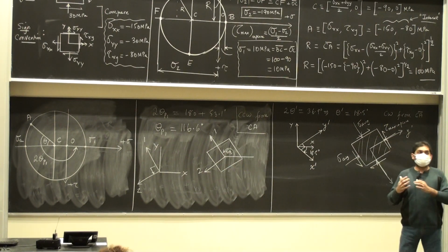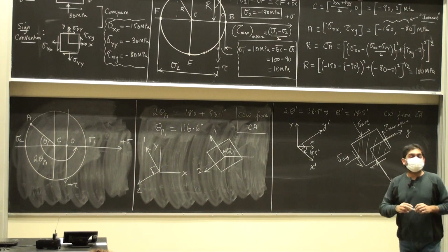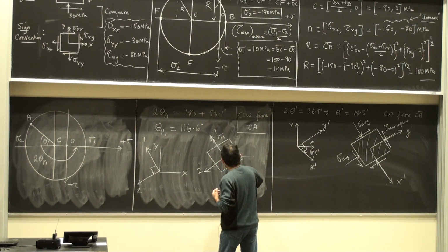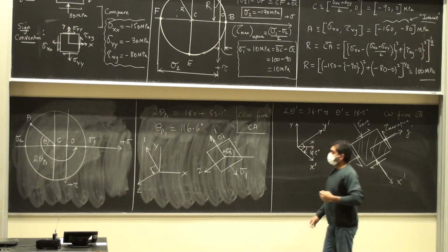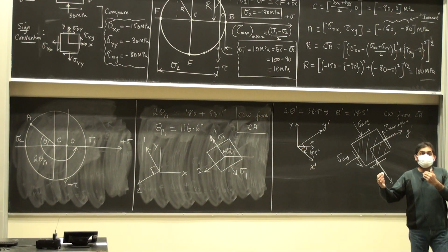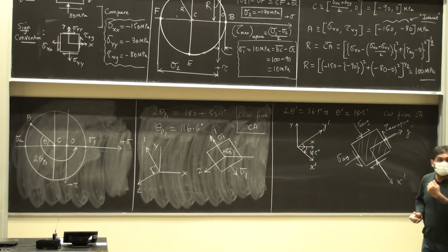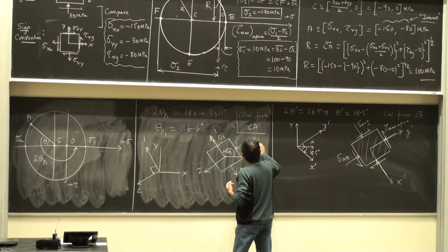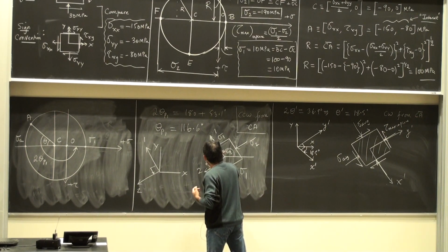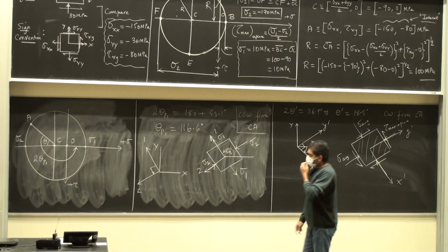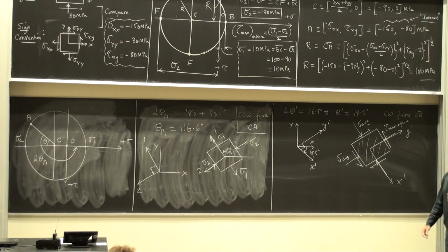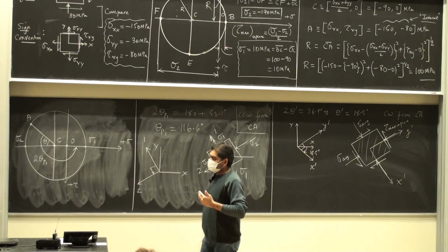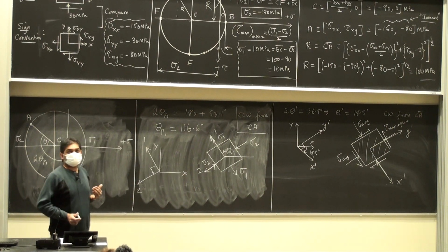On the 1 axis, what am I going to have? I'm going to have tensile stresses, 10 megapascals. This is sigma 1. On the 2 axis, I'm going to sigma 2, which means that I'm going to have compressive stresses, which is now whatever, minus 190 or something. So that's sigma 2. And by the mathematical nature in which the principal stresses are defined, there will be no shear stresses on this plane.